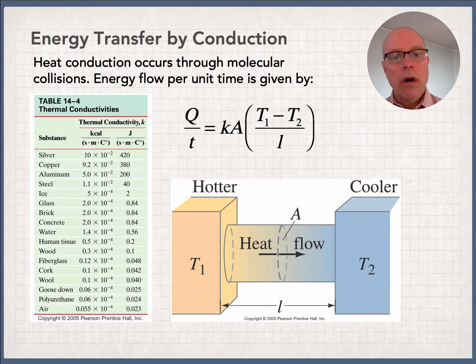So in this slide, I'm giving you all of the technical details that you need to know when you think about conduction. So let's dive in on the formula first, and I'll explain that. Q over t is the amount of heat, Q, per time that flows from a material. A is the area of the two surfaces that are joined. So if I point down to my diagram, you can see that I have one material that's warm, and we're going to call that T1. Another material is cold. So this could be a framing member where this part is the part that's inside the building, and this is the part that's on the edge, maybe against the brick of the outside of the building. And what's going to happen is heat's going to flow from hot to cold on this. So I've got my two temperatures, T1 and T2.